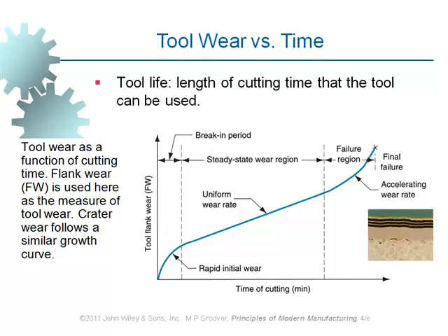In industry, we've got to make use of the cutting tool, starting from here all the way up to here, and replace the cutting tool before it fails. Before it fails. Because if it fails, it may do what? It may have a negative impact on the surface of the very last part, and that may actually scrap the part.